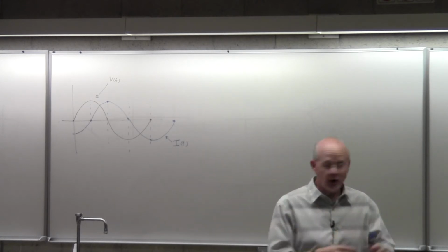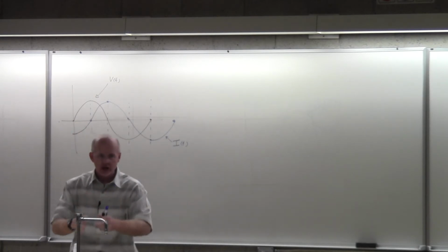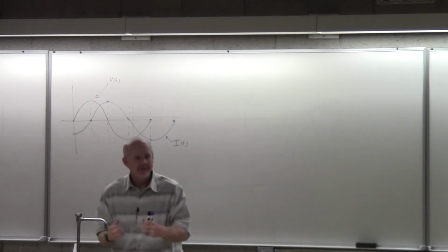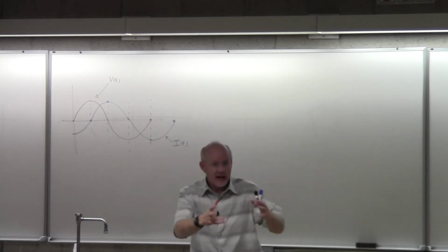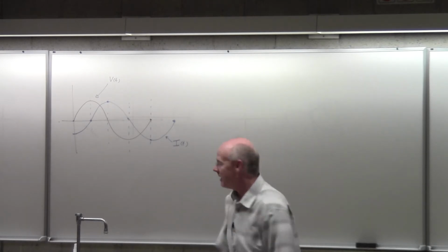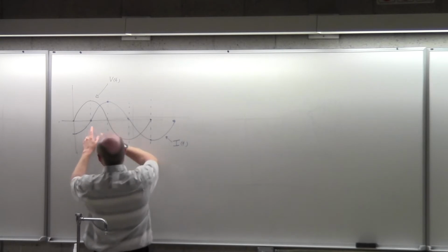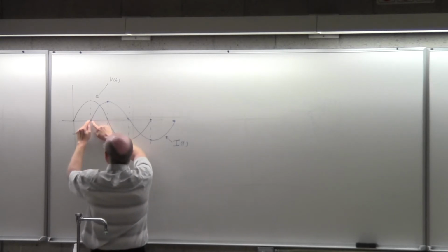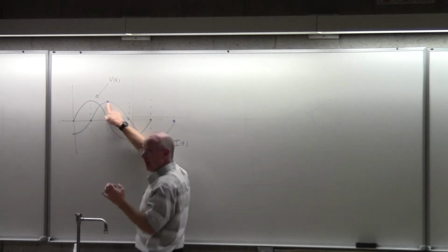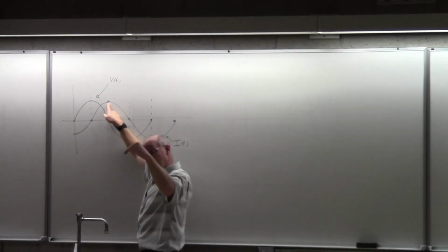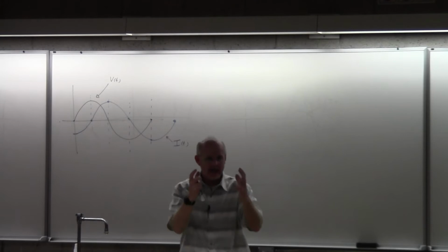It's not when you have the current, it's when you're trying to put the current in. So as you try to put the current in, that's what's happening right here. At the very beginning, you're trying to shove the current into the inductor. It's not there yet. You don't have the current yet. It's going to take a little while later before you get the current. And so what ends up happening is something like I guess here, you're trying to change the current by a lot and you get a lot of voltage. It's later on, you get up here to where the current has reached its peak and is tapering off, is where you're not changing the current. You don't expect it to get an EMF.